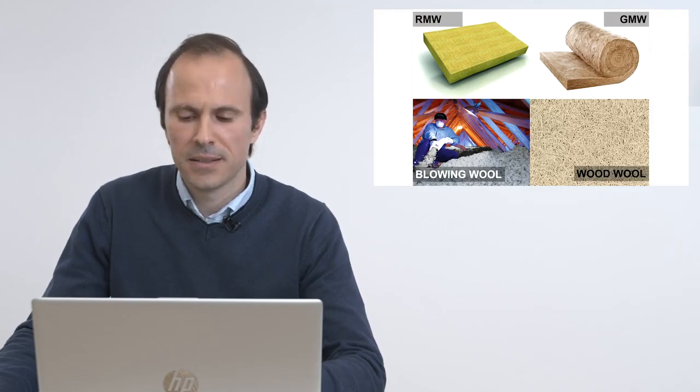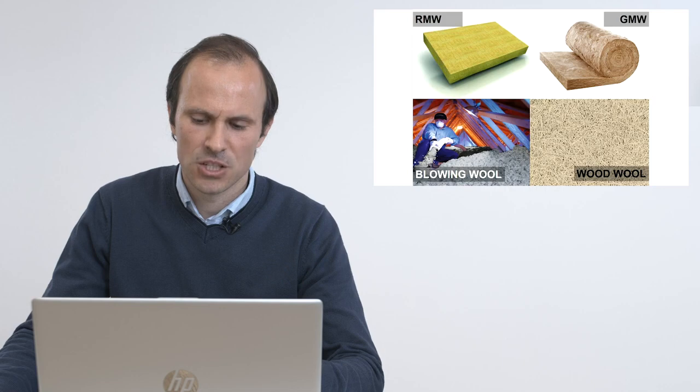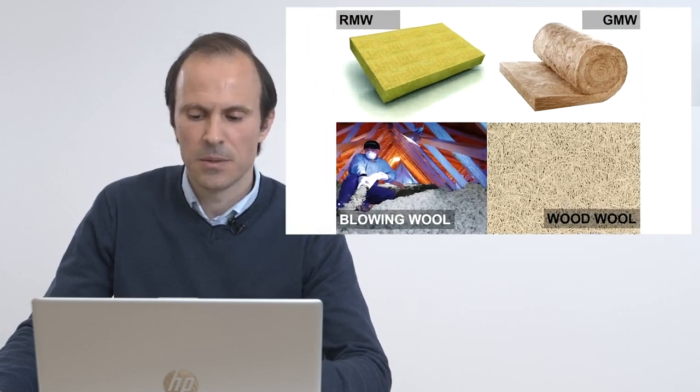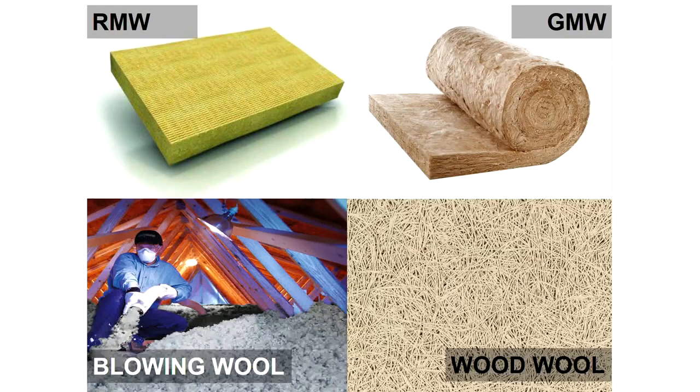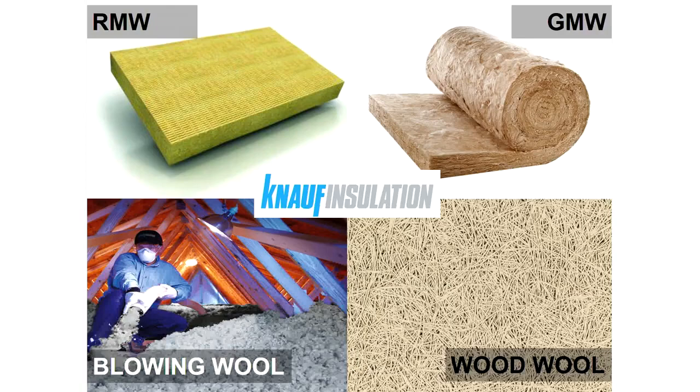When mineral wool materials are discussed, there is usually a strong debate around which material is the best. Is that the wood wool? Is that glass mineral wool? Rock mineral wool? So what I always like to point out and emphasize is that each of these materials has its own strong points. So it's up to the particular application to define which material will be the best. And that's again one of the strong points for us at Knauf Insulation, because we are manufacturing all these mineral wool products: blowing wool, wood wool, rock mineral wool, and glass mineral wool. So we are able to recommend a product which actually suits a certain application the best.